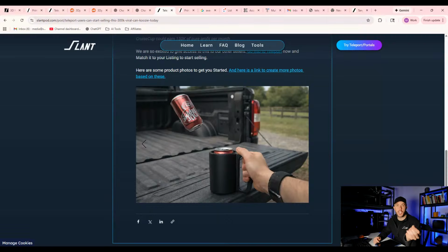But if you need to go down super small, I would say go down to like 0.2. That's generally fine. We can go down to 0.1, but I don't recommend it because it becomes very unstable. Because again, like a really sticky PLA will stick differently than like a matte PLA, and now your parts change.